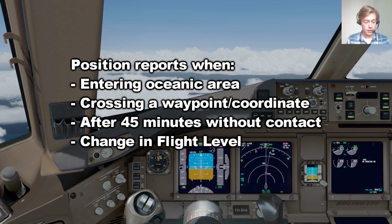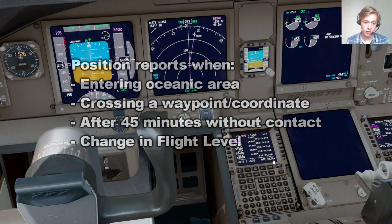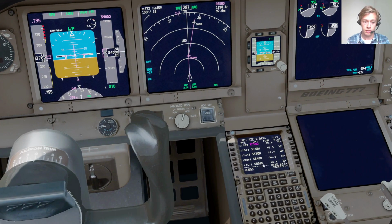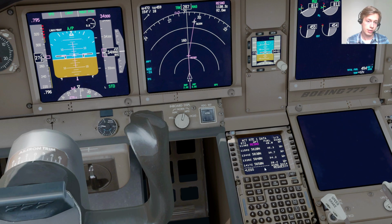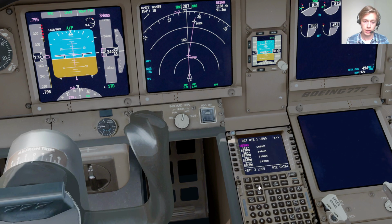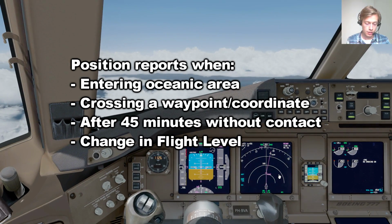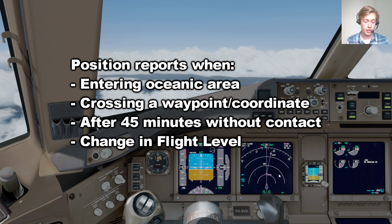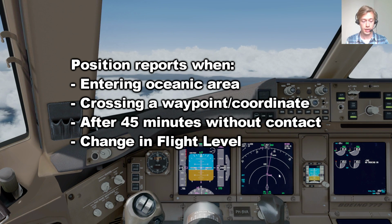report, okay? Now in practice, if you look at the NAT coordinates right here in the route data, you will see that the time between them is usually not more than 45 minutes, or very close to 45 minutes. So in general, it should be fine to just do a position report at the coordinates, okay? But just keep in mind that you have to do this. Also, when you are given a change of flight level or request a change in flight level, you also have to do a position report, okay?